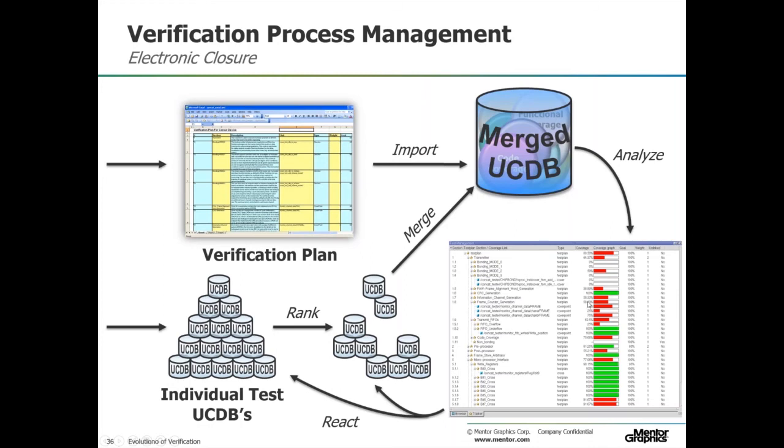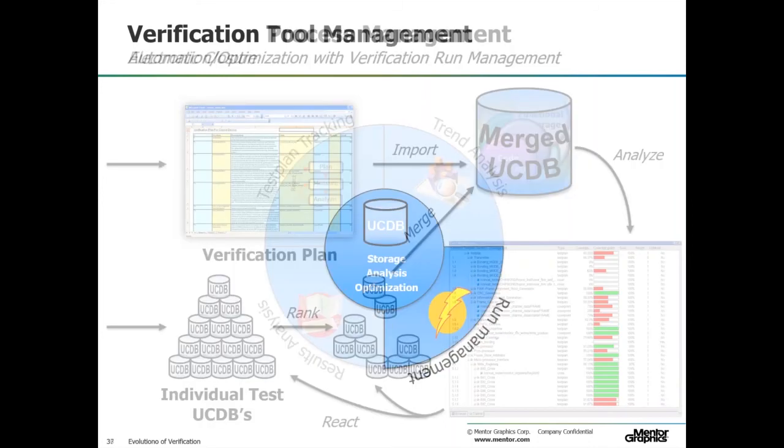Maybe my frame counter, it says I'm 58%, and then I can look, why am I 58%? Well, it's because these different objects have different amount of coverage, and this all becomes a cumulative roll-up into the transmitter section. And then each section has its own roll-up into there, and then, you know, it rolls up to each section above it. And so right now, I can see that I've 80% covered my test plan. Well, I got to go cover those objects that aren't covered. So that's what doing metric-driven verification is about.